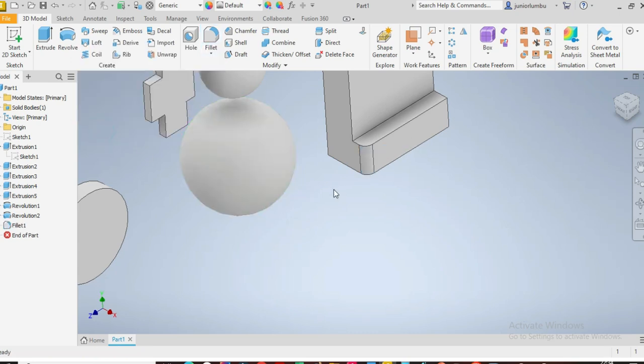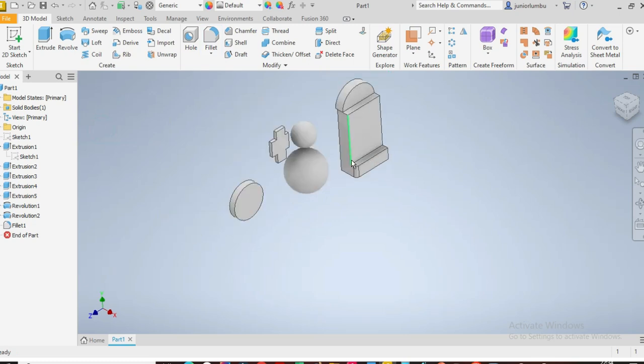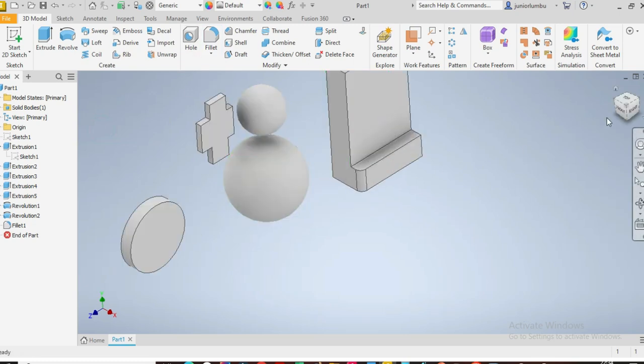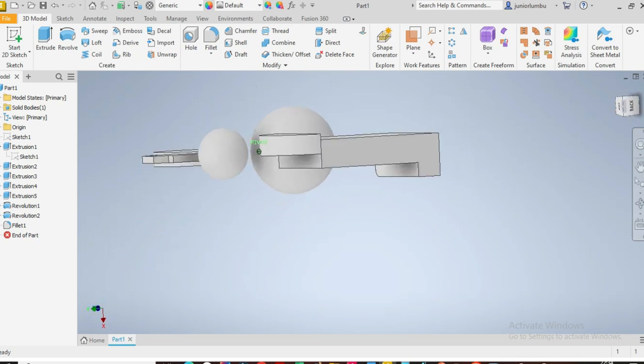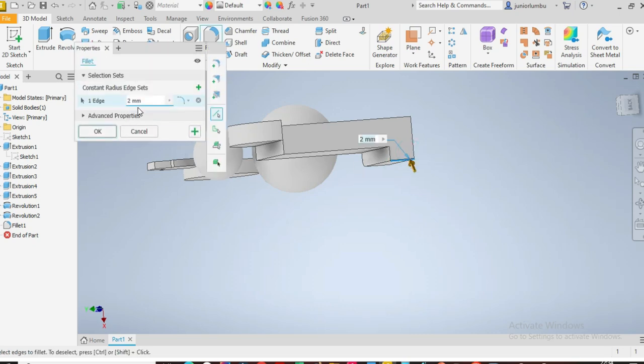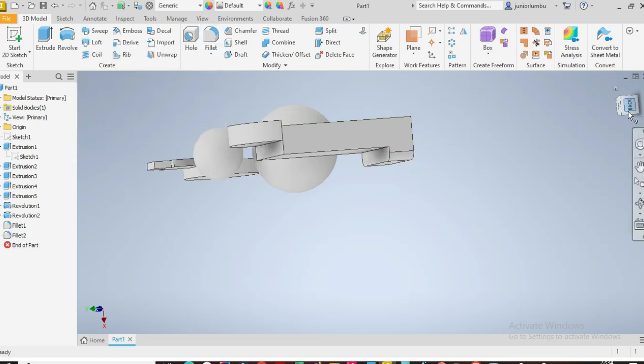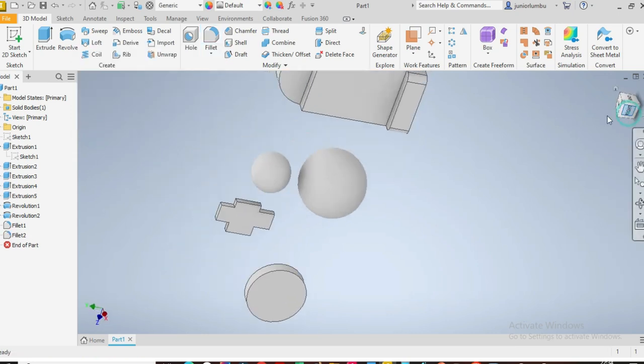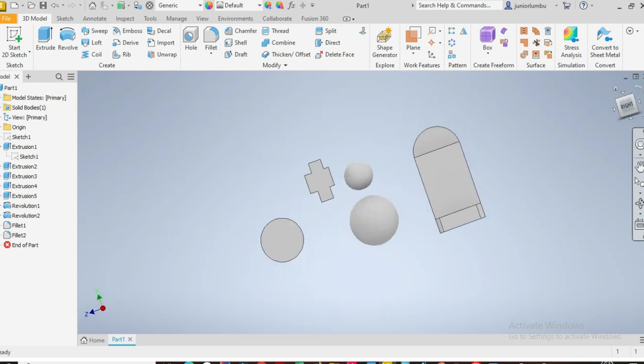The same way, you don't have to click on the tool there. You can also come on the corner. By doing this, I click on there, then I have the fillet option. I can choose my radius. This time I'm going to say 30mm radius, then I have my fillets there. So this is how you turn it.